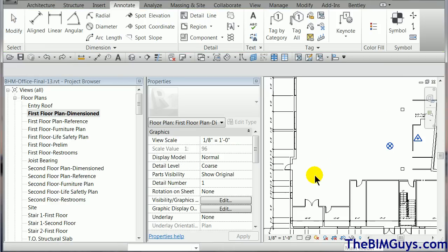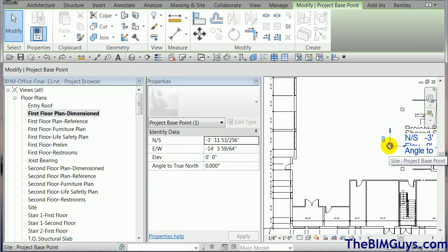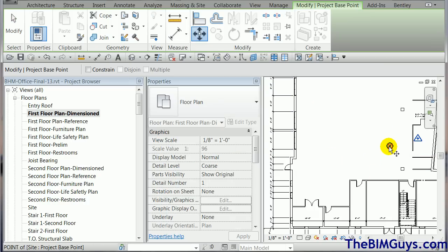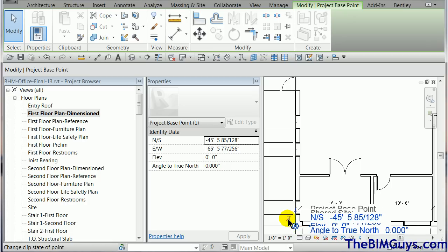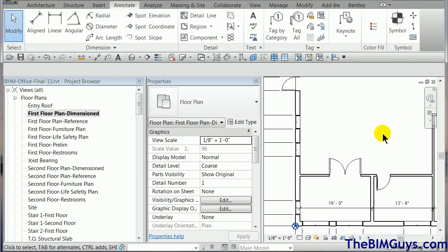Now what I'm going to do is I again grab the point, unpaperclip it. Now I'm going to use the move command, so I'm accurate. I'm going to roll over that, it picks up on the point, and I'm going to go to the corner of the building. So it pops it right on that corner, and I can check. Now at this point, I'm going to lock it. Now you'll notice these numbers, what is that all about? That's in reference to the actual site. But let's check it out now. So we got the corner of the building.